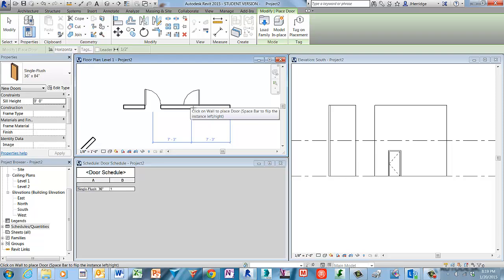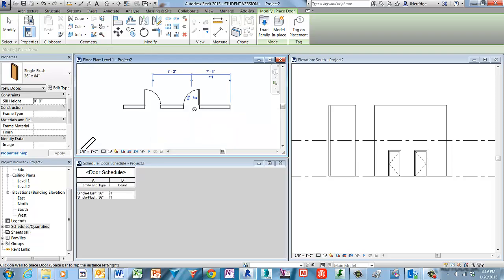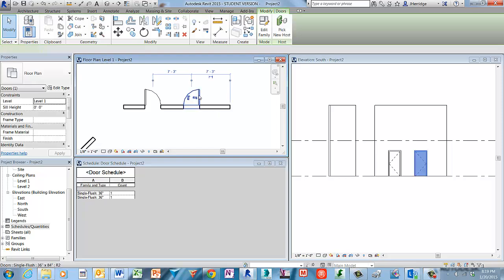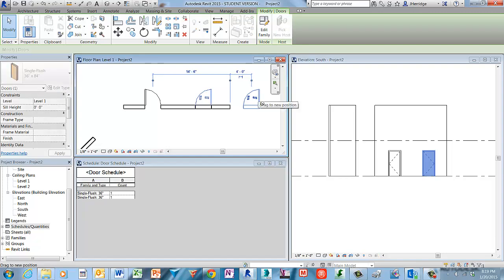Now, if I select the door and choose create similar, I can place another instance of the door in that same wall. You'll notice that there's flip grips that appear inside the opening of the door. They perform a function when you left click to flip the door in that particular direction. Likewise, we can click and drag the door to relocate it manually.